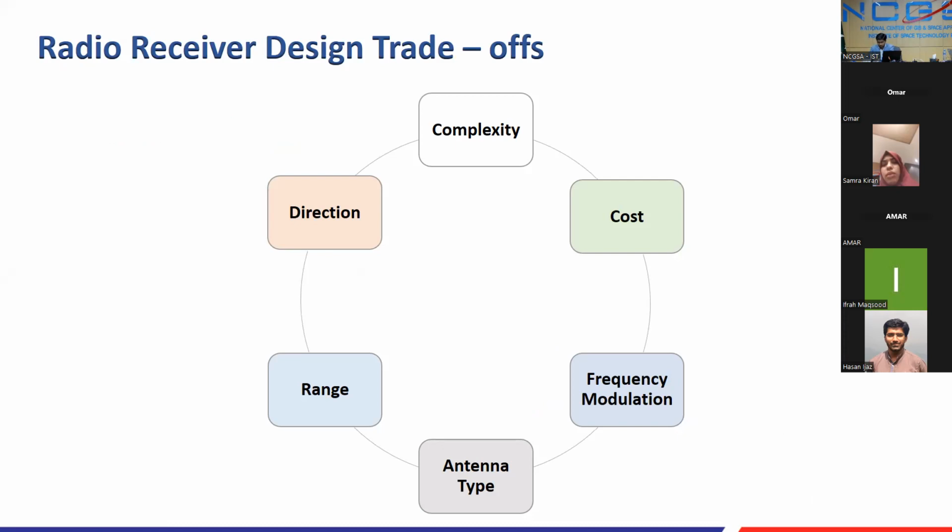We discussed the different configurations of the receiver: homodyne architecture, heterodyne, super heterodyne, all digital receiver. I have not mentioned there is another system as well, DLVA, digital log video amplifier, where you are only interested in the envelope of the signal. That is the same topology we previously used for AM radios. You are only interested in the amplitude. So there is another type of receiver as well.